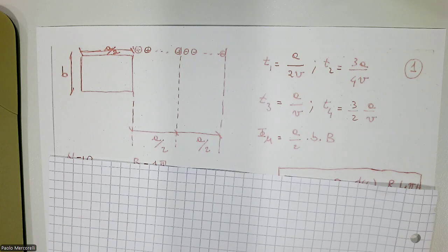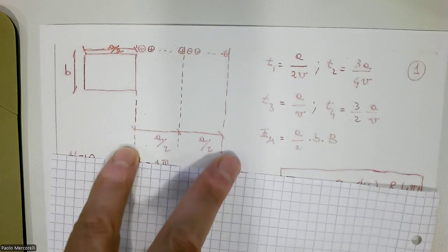I showed you this valve which we used in the exhaust, better to say the intake valve, but of course we simulated also the exhaust valve of the cylinder, which in one design or in two designs had a really rectangular section, a rectangular coil with dimension B and dimension A divided 2. Why A divided 2? Because I am considering here